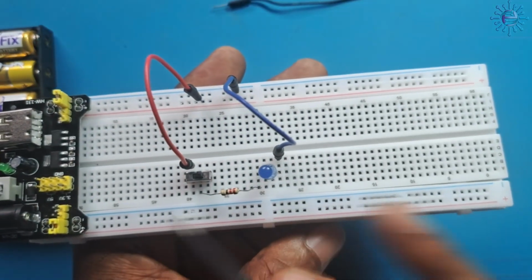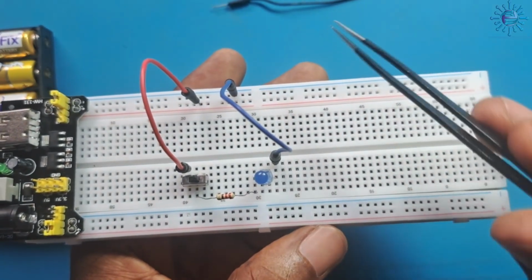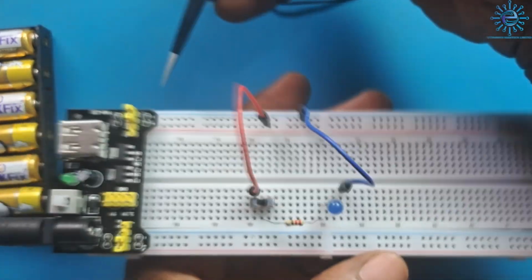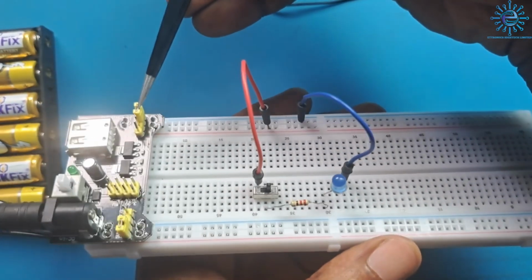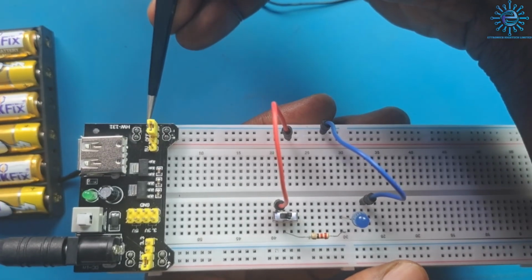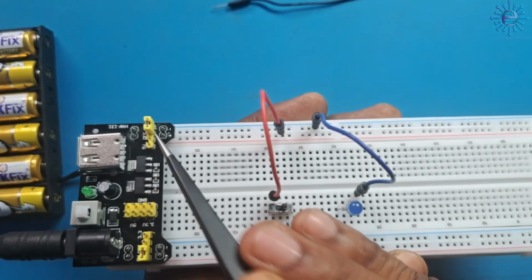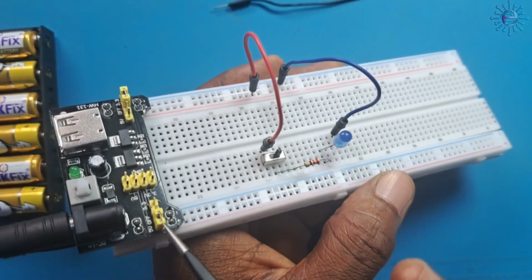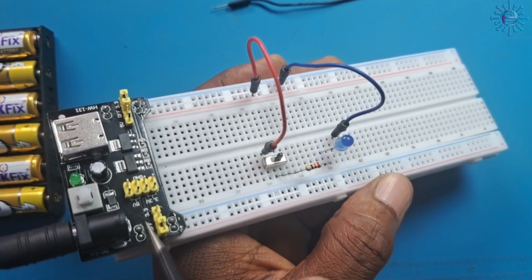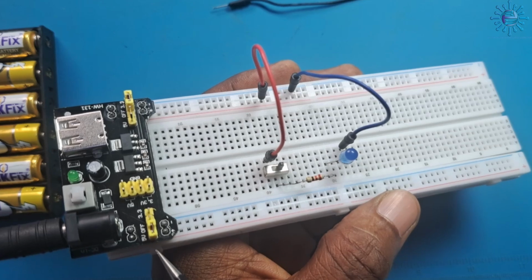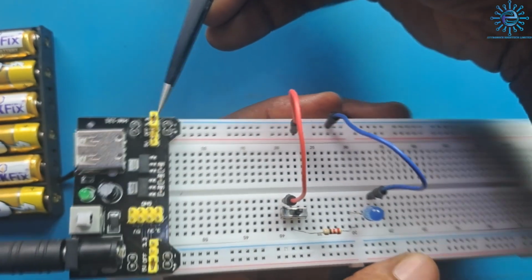What we have here is also what we have here. However, what determines the voltage that we will get here and here is the position we fixed our jumper wire. So if we fix the jumper wire here, it means that we are going to get 3.3 volts. But if we switch it to this point, we will get 5 volts. The same thing is what we have here. If we switch this jumper wire from this 5 volts to this 3.3 volts, we will get 3.3 volts here. But as it is now, here we are getting 5 volts, and here we are getting 3.3 volts. So our circuit is ready.